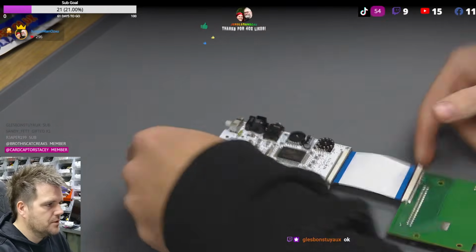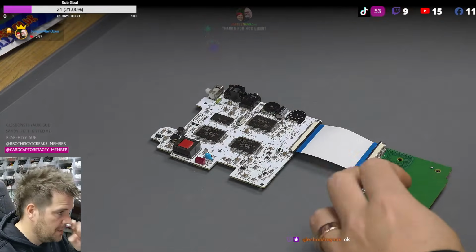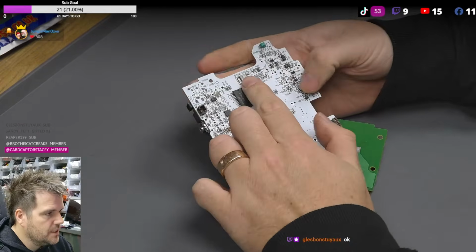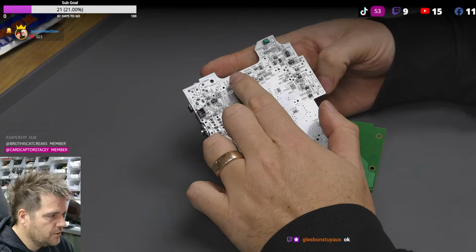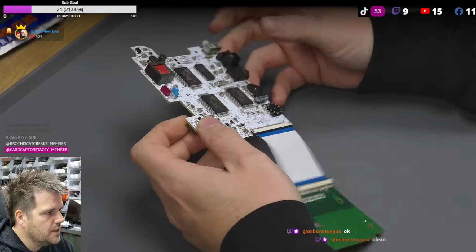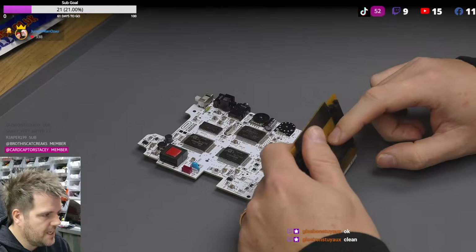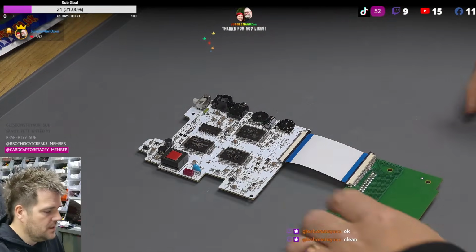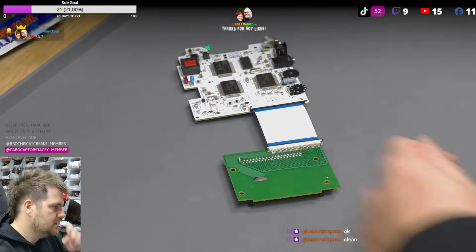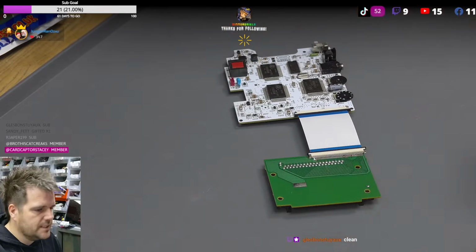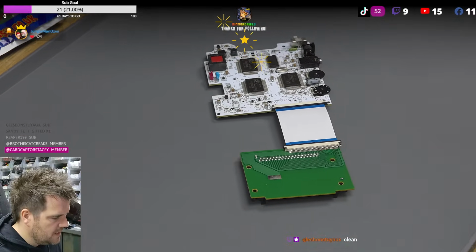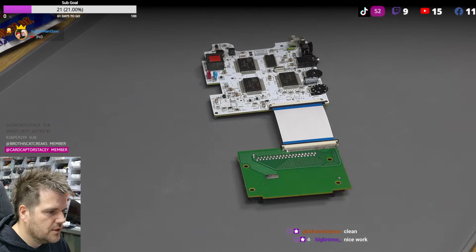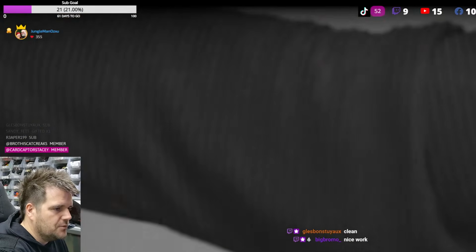this might boot. So I'll bring this up later on stream. We'll have to apply power slowly and make sure the regulation circuit works and we don't overvolt, because this is obviously the first check. If we then get 5 volts, we can put a game in, probably put headphones in and listen for game audio maybe. But I'll try and bring this up later. But for now, I'm going to see if I can go for a coffee or whether the message has run off. So sorry for the darting, guys, but I don't want to miss that.